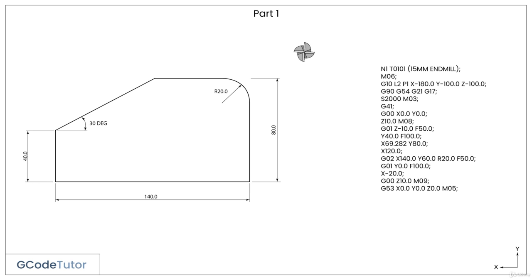I now tell the cutter to go back to our machine datum position, which is also our tool change position. The G53 sets our datum back to the machine datum away from our work shift datum that we defined with G54. Now we can give the dimensions x0, y0 and z0, and the machine takes them from our G53 datum. M05 tells the cutter to stop rotating.